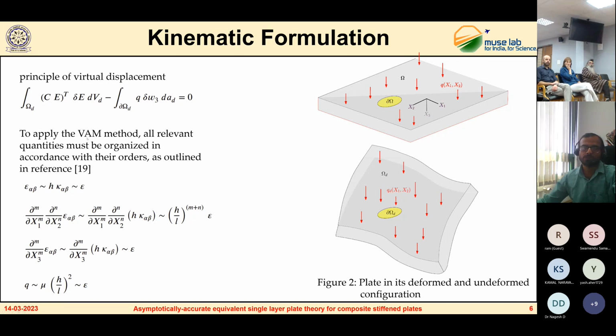So in the WAM approach, we first arrange all the terms of this statement as per their order of significance. In the first perturbation, we take the most significant portion of this statement and find out the corresponding Euler equations and boundary conditions. We solve these Euler equations considering the boundary conditions and get a warping vector W. But this warping vector W is not complete, as we are not taking the full energy into account.